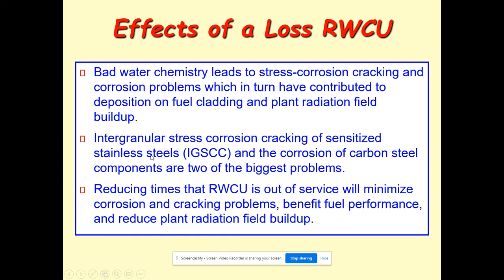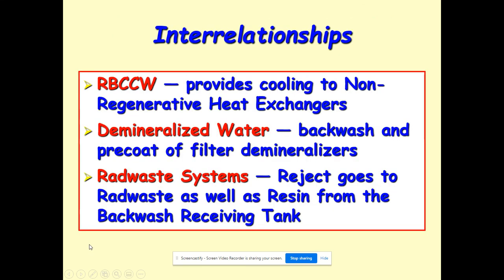Another issue is you're going to start to get intergranular stress corrosion cracking. So cracking, we'll just stick with that, right? You're going to get small cracks in the stainless steel because where this corrosion starts to build up, it's going to weaken the metal a little bit. And so you want to keep reactor water cleanup in service as much as possible just to prevent any potential issues.